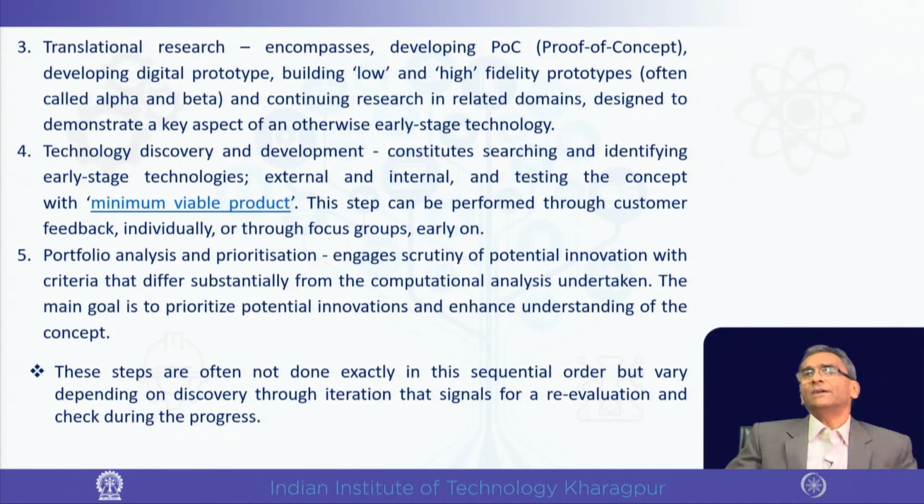Say, for example, if someone is trying to check a gear or a mechanism, whether it is functioning, one can use a 3D printed plastic or maybe wooden one to check whether the mechanism works. But in actual practice, to withstand the real load, maybe full scale alloy steel material is to be used, which is the beta prototyping.